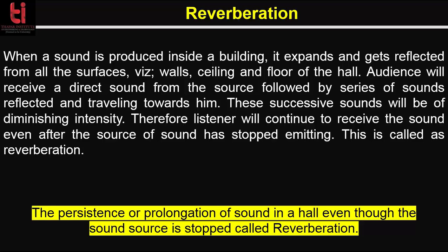Now we will talk about reverberation, a very important term in architectural acoustics. Reverberation in acoustics is the persistence of sound after the sound is produced. When a sound is produced inside a building, it expands and gets reflected from all the surfaces, that is, from the walls, ceiling and floor of the hall.